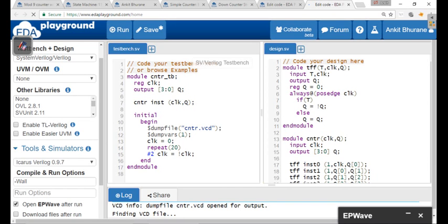What I am saying is this q, initially it will be of any value. It may be a don't care condition. Even if you increment don't care, it will be don't care. We don't want that. So I need to specify the q some value, let's say it's 0. I can't specify that here in the main module. Why? Because we can't assign the value to a reg if you create an instance. It must be a wire. So what we are doing is simply defining that q equal to 0 in the flip-flop definition itself.